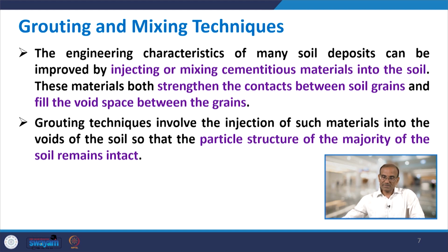So, coming to grouting and mixing techniques, the engineering characteristics of many soil deposits can be improved by injecting or mixing stabilizing materials into the soil. So, here you can inject inside the soil or you can mix inside the soil. These materials both strengthen the contacts between soil grains and fill the void space between the grains.